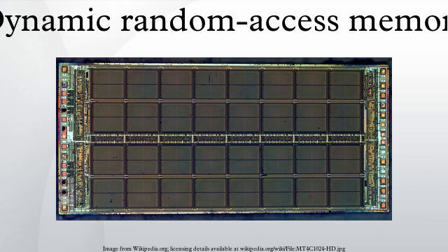Refresh rate. Typically, manufacturers specify that each row must have its storage cell capacitors refreshed every 64 ms or less, as defined by the JEDEC standard. Refresh logic is provided in a DRAM controller which automates the periodic refresh. Stated differently, no software or other hardware has to perform it.